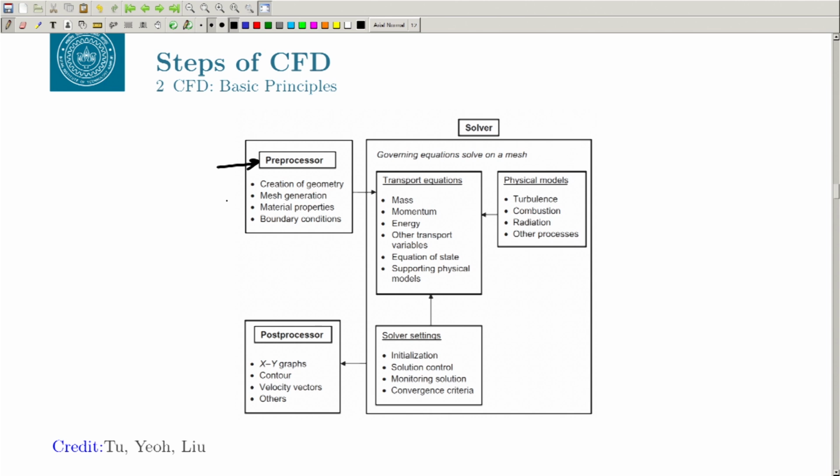For example, if you are designing an aerofoil or a turbine blade, you do not want a discontinuity in the shape that triggers the flow to become transitional or turbulent. You do not desire all those things. So geometry creation is a very important step where you need to make sure that it follows C2 continuity on the surface, and it does not have any leak, it is watertight and all those things.